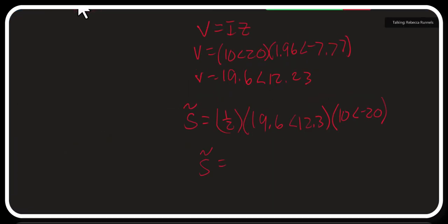And then when we get that complex power and we multiply that out, we got a value of, help me out here, otherwise I'll have to scroll up to all the messy work and then they'll know that I'm pretending like I don't make mistakes. 98 angle negative 7.7, which if we write that in rectangular gives us 97.1 minus j13.2.